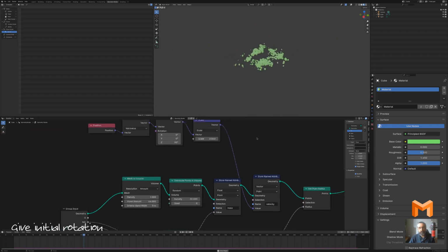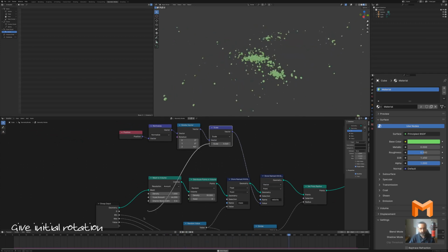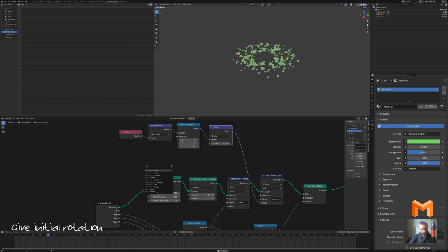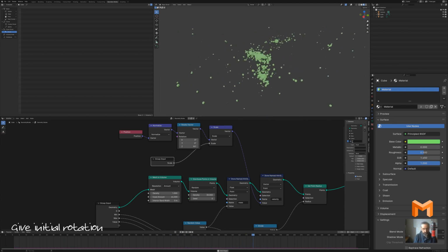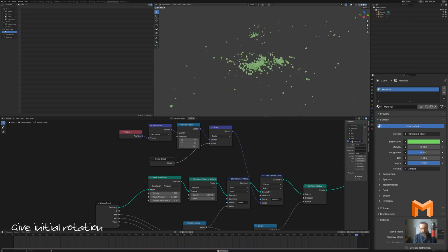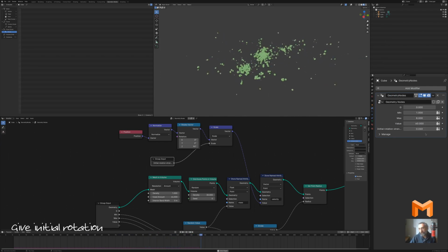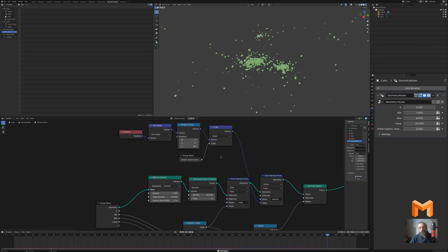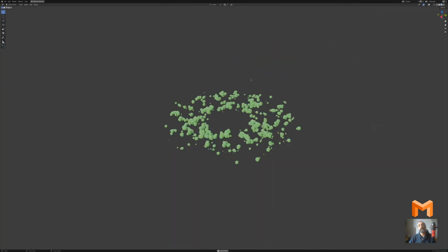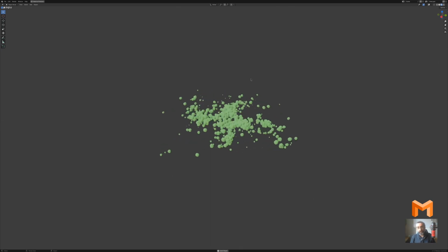And one more time, you can connect this to the input if you don't want too many links crossing together. Let's add the group input like this, and this is not the scale. This is, for example, the initial rotation strength, like that. And so inside your geometry nodes tab here, you can change the strength of the rotation here, and this is cool. Okay, so this is the end, and I hope that my video shows you some nice tricks to create some simulation.